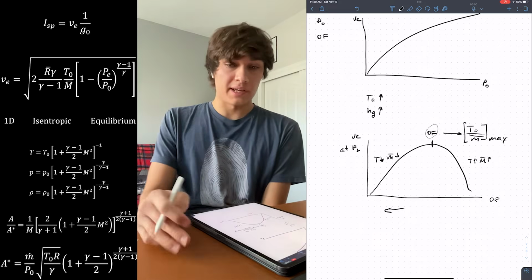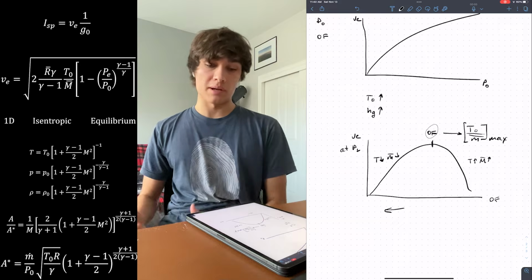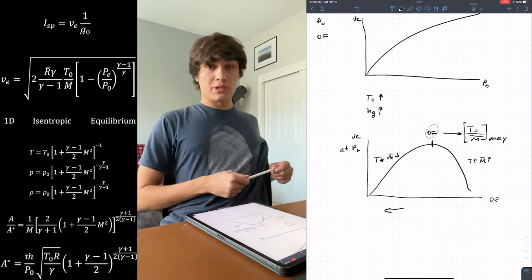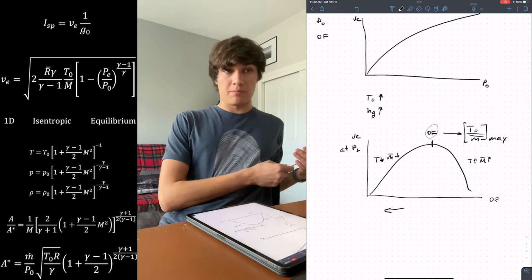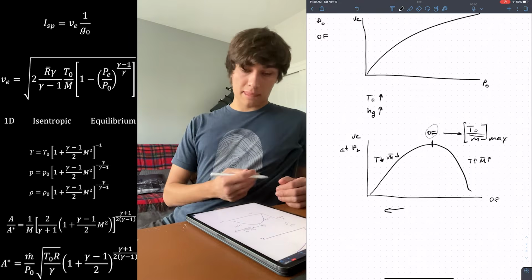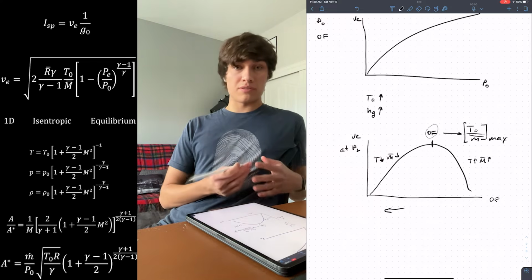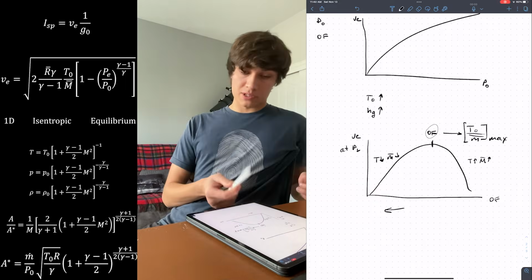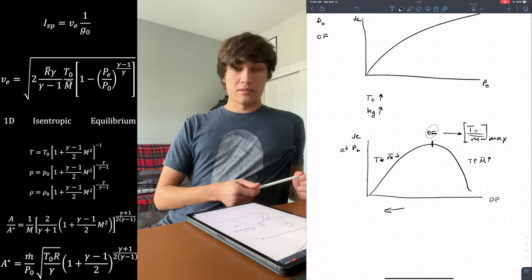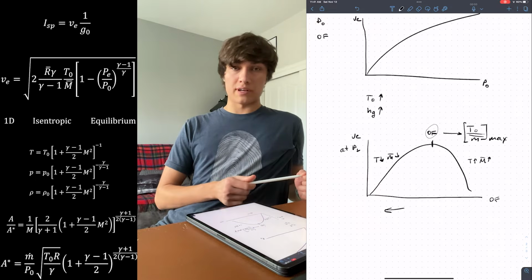This will vary significantly by chemistry. So for example, hydrogen, because hydrogen is such a light molecule, the ideal oxidizer-to-fuel ratio is very biased towards a fuel-rich mixture by, let's say, kerosene standards. It's in the 5-to-1 range, but we describe things that are more than 5-to-1 as oxidizer-rich and things that are less than 5-to-1 as fuel-rich because of this ideal oxidizer-to-fuel ratio. For kerosene, especially in our pressure ranges, it's around 2.5. And for other propellants, it varies.